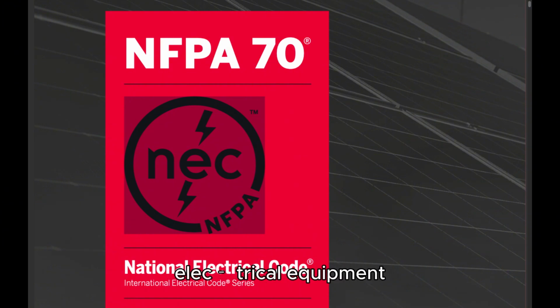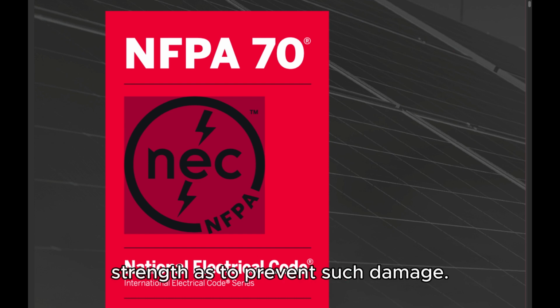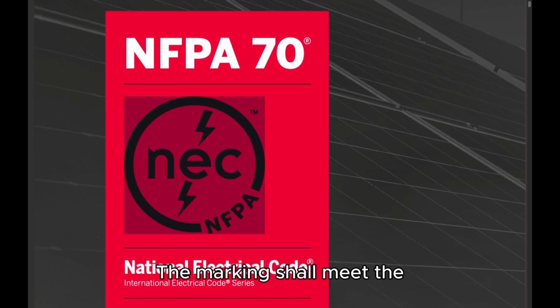Live parts of electrical equipment operating at 50 to 1000 volts nominal shall be guarded against accidental contact by approved enclosures, or by the means in 110.27(A). (B) Prevent physical damage. In locations where electrical equipment is likely to be exposed to physical damage, enclosures or guards shall be so arranged and of such strength as to prevent such damage. (C) Warning signs. Entrances to rooms and other guarded locations that contain exposed live parts shall be marked with conspicuous warning signs forbidding unqualified persons to enter. The marking shall meet the requirements in 110.21(B).